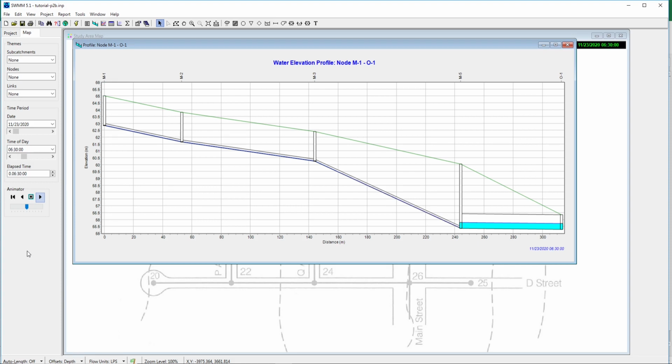day. And as we can see in all the pipes except the larger one, the values of the flow is very small. But of course we cannot use a pipe diameter smaller than 150 millimeters because of the specifications given in the question. So we have to use the minimum pipe diameter which we have chosen, and based on that we can see that in the cross section we don't see much changes there. So let's look at the other results now.